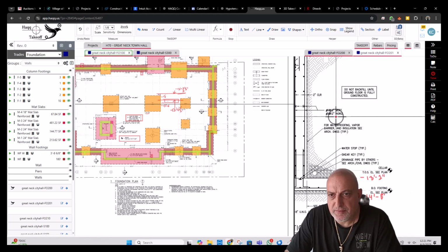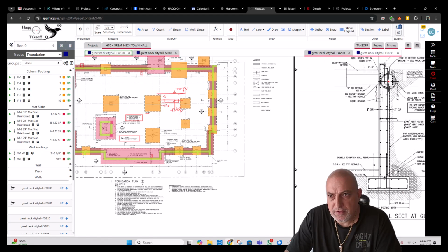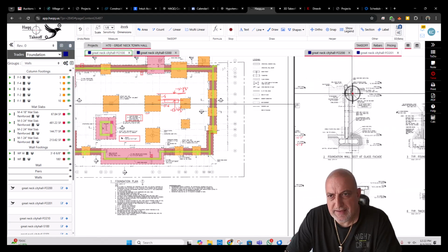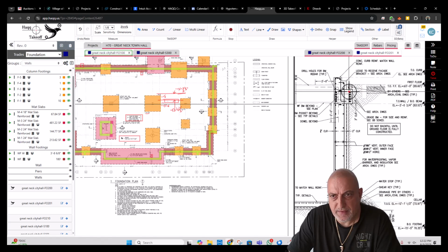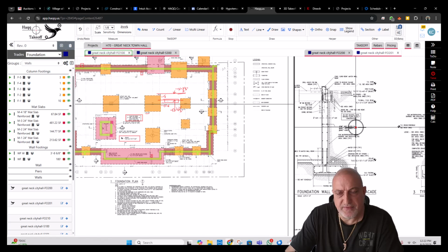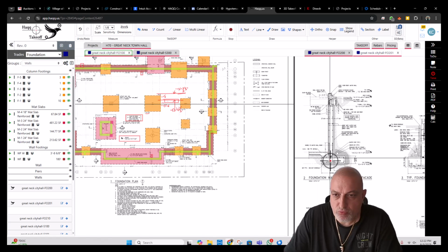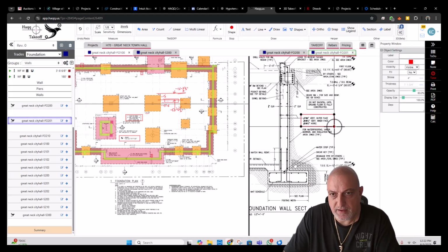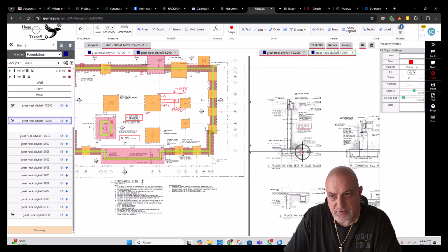Any change in the reinforcing before we get into it? Number 5 horizontal, number 6 verticals. And this is the grade beam at the top. We got dowels here. Something going on here. At the glass facade, it is going higher. It looks like a curb on top of the grade beam. And the reinforcing is different too. So we actually didn't do a good job here. This has different reinforcing. I didn't pay enough attention, I believe. Alright, this is different. Section 2 is different.